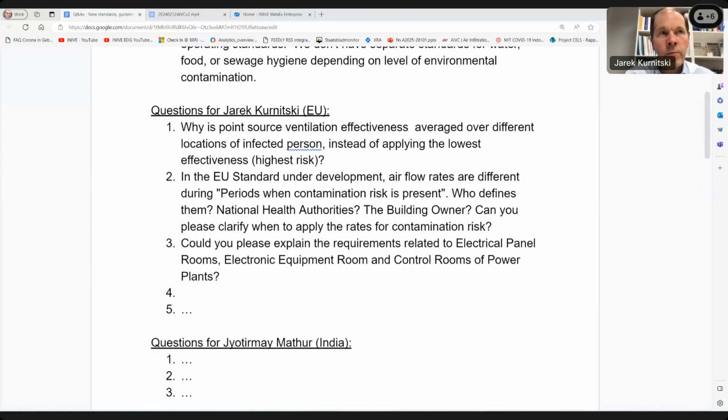So if we speak about equipment which is with higher capacity, so bigger air handling units, perhaps some improved air distribution, when we mostly speak about increased investment cost. But this can also provide energy savings, because if the system is mostly operated on demand-based, then a high capacity system can be more effective at low air speeds.